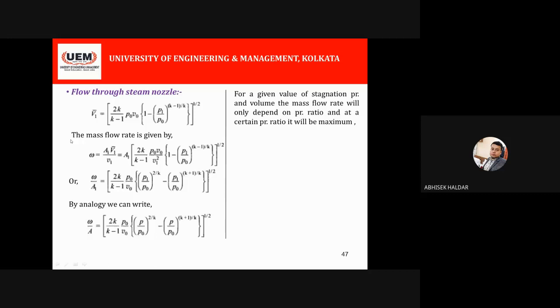That means my velocity is 0. Not exactly, but we can consider it as a stagnation state at the inlet condition. That's why the inlet condition is always pre-assumed as the stagnation pressure and volume, as you can see several times in your book. Is this point clear?